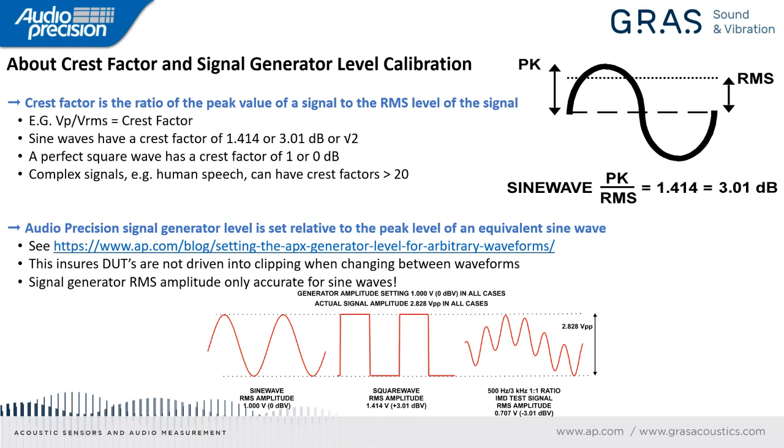Great, thanks, Dan. And one more question, is there any unit as dBA, or lowercase d, uppercase B, lowercase a? Sure, and I'll talk about that in a moment, but the simple answer is, unfortunately, a little bit confusing, but the most common understanding when you see dBA is it is dB SPL, so dB sound pressure level, so dB relative to 20 micropascals, that has had an A weighting filter applied to it.